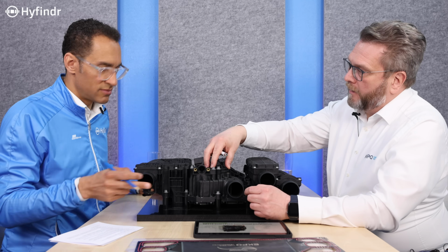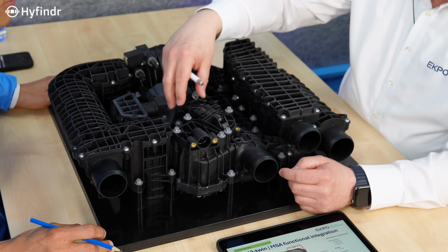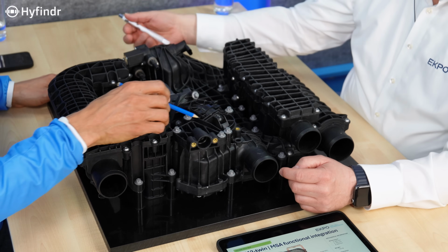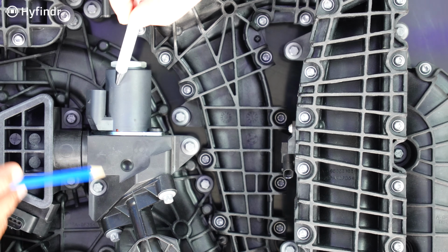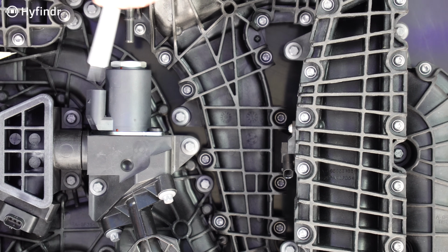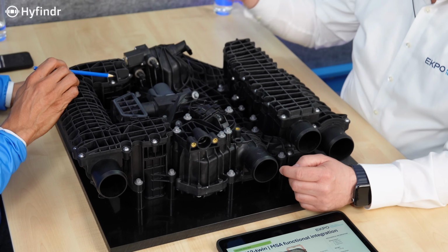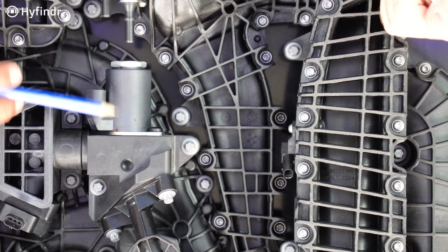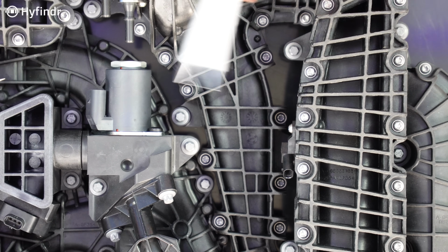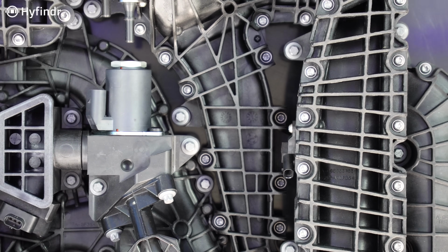Yes, that's the thermal topic we had earlier. And then it's coming to the pressure control valve. You can see it from here. There we control the flow of the hydrogen according to the amount we consume. We talked about earlier, a solenoid? It's a solenoid, exactly. Controlled with this pressure sensor right here.